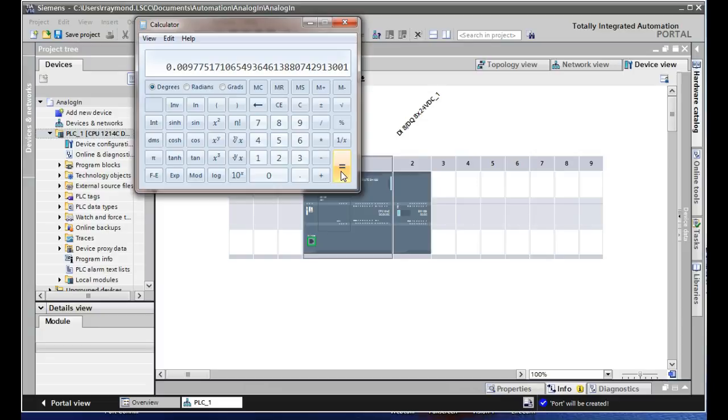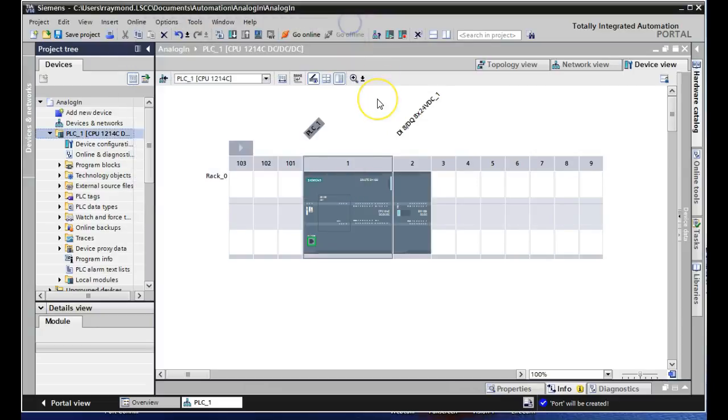Well, A to D converters have been around so long that, of course, the more they move up the field inside PLCs, the more likelihood they're going to add instructions that allow us to do the math for us, right? So Siemens has an instruction called normalize, which basically means we can take something and convert it over to something else. So I can take the count and convert it over to the fraction that represents.